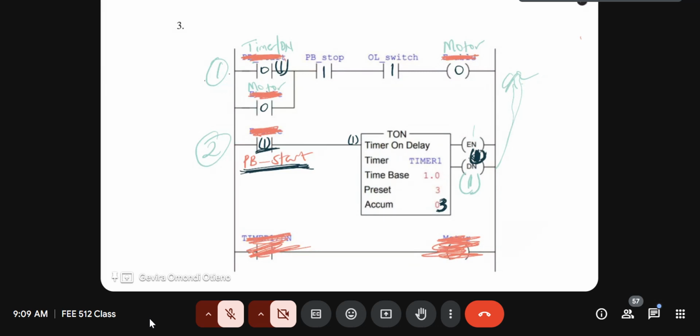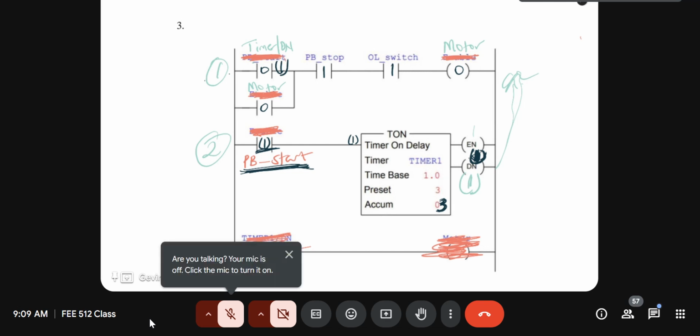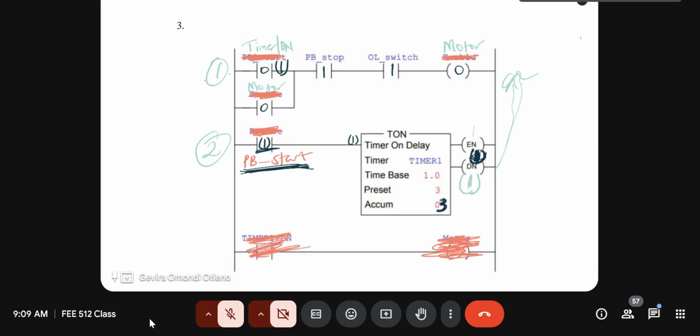Yeah, I'd also say it should still work, because from the scan cycle, the first step is to read and check all inputs. So it doesn't matter where it will be. Brilliant. Thank you very much. Actually, that's what I was looking for. Sometimes I was waiting for the word scan cycle. And we know that our scan cycle is usually read, execute, and then update.